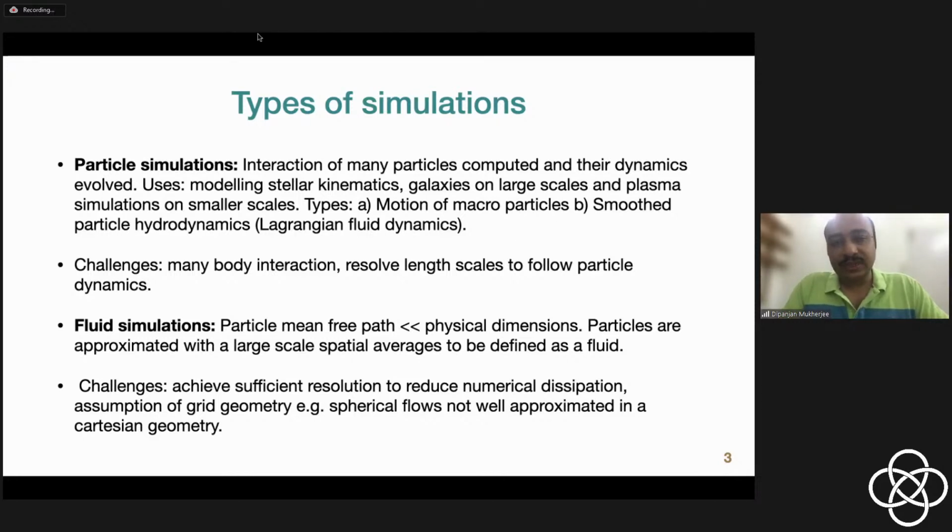And in your fluid dynamics lecture, I am sure you've now heard this term about Lagrangian motion and Eulerian motion. In Eulerian motion, we divide the background fluid in a grid. And then we see how the properties of the fluid are changing at different locations in space. But in the Lagrangian motion, we discretize the fluid, or represent the fluid all around us, in terms of particles, where a single point in space represents a blob of fluid, for example. And then we follow the motions of that fluid blob. And that is called smooth particle hydrodynamics.